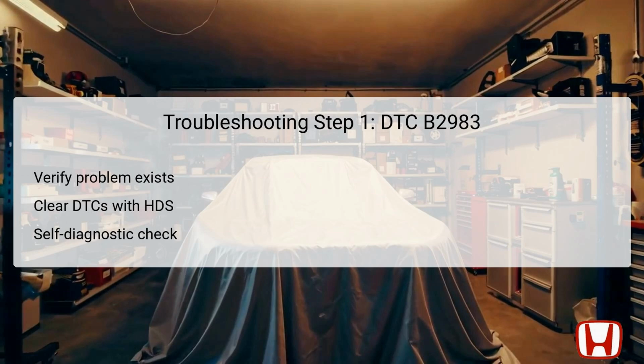The first step in troubleshooting DTC B2983 is to verify the existence of the problem through the Honda Diagnostics System, HDS. This involves clearing any stored diagnostic trouble codes and then conducting a self-diagnostic check with the HDS or the climate control unit. After the diagnostic has completed, it's essential to check for any DTCs that reappear. If DTC B2983 or indicator 57 displays again, it confirms an underlying issue with the recirculation control motor circuit.